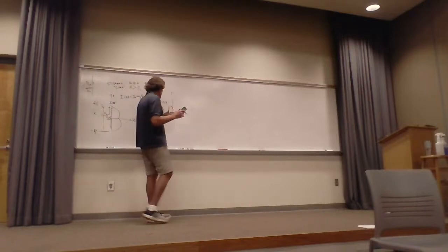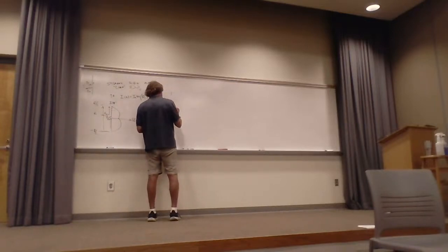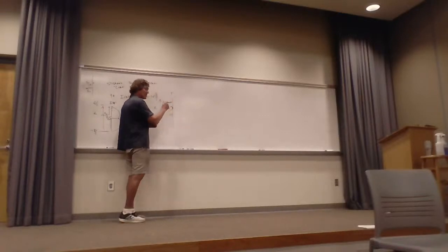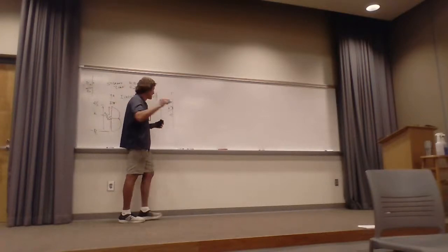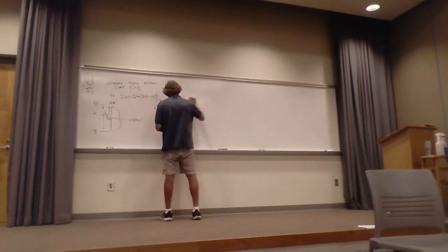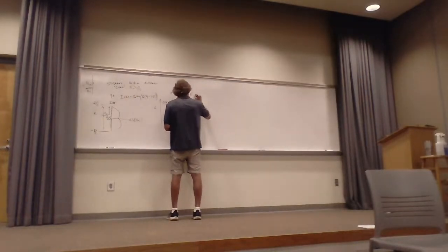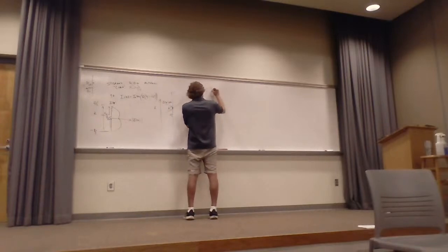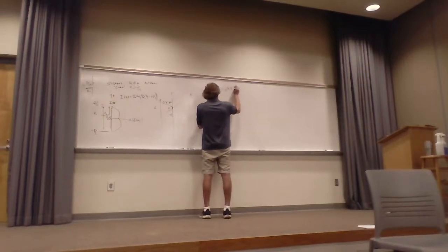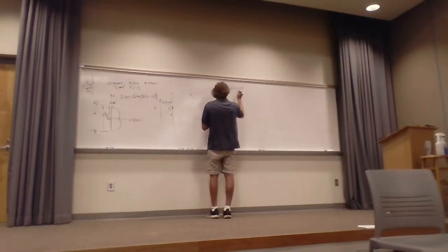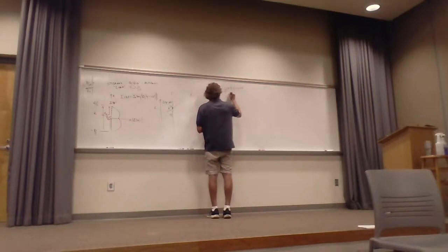All right. Now, if I have this differential length here, I have really I dz here. Y'all follow me? That looks like a dipole antenna. It looks like a short dipole, doesn't it, with length dz. So I can say if I come out a distance r prime, that the differential electric field from that, dE, would be equal to j eta beta times I of Z times dz over 4 pi r.